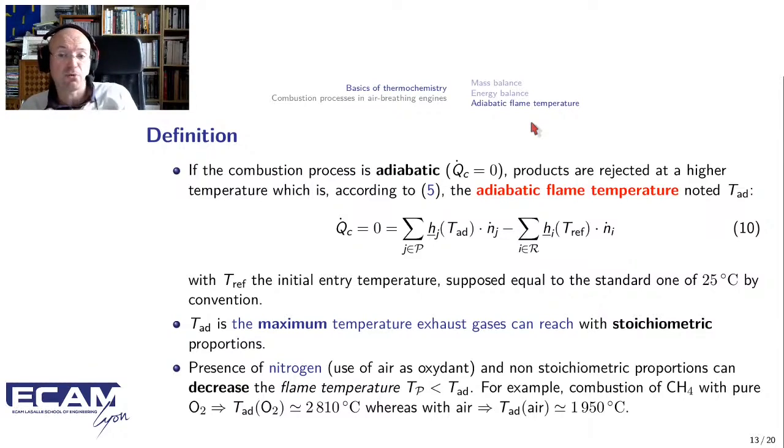It's exactly the same for air. For example, consider here you have methane, you mix methane with air, so with oxygen and nitrogen, you make them burn in a completely adiabatic system. Also, you will reach a temperature of almost 2000 degrees. And for a lot of practical applications in gas turbines and in aircraft engines, this is really too high, because your system is supposed to work.